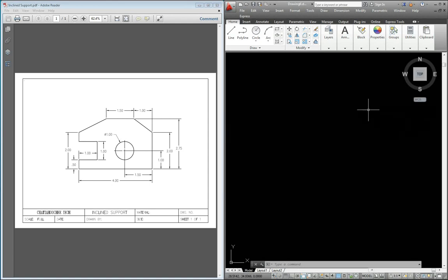Okay, and again, snap mode, not talking about object snap, I'm talking about the actual grid snap. Okay, so let's start off drawing this with direct distance. So I'm going to start the line command, and then anywhere in model space I'm just going to left click, and you know what, I actually need polar turned on. Let's turn on polar so I can get these nice, actually let's use ortho because we haven't used ortho yet. So I'm going to click on ortho. Remember, ortho allows us to go straight up and down and straight left to right, which is exactly what we want to do. So I just want to pull my crosshairs to the right and then type 4 and then enter.